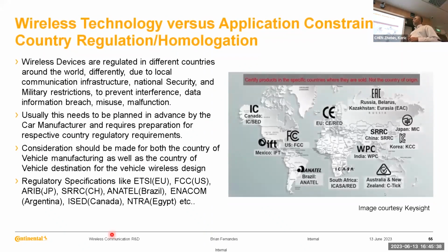And then, of course, this is usually the last aspect to consider, but usually the most expensive and the most important, because depending on where your product is going to, you have to meet the regulatory requirements of that country, which defines which frequencies can be used, how much power can be used, how often can you use that wireless communication in that country. And usually what this means is that a design that may be really useful and really efficient and really cost effective in one country may not be allowed in another country at all. So then redesigning that would take significant efforts and would increase the cost significantly.